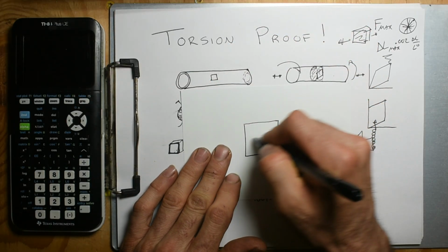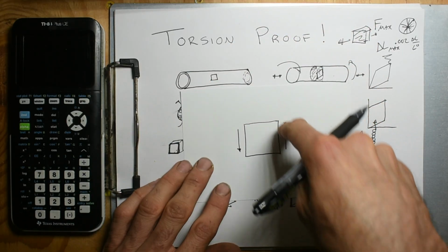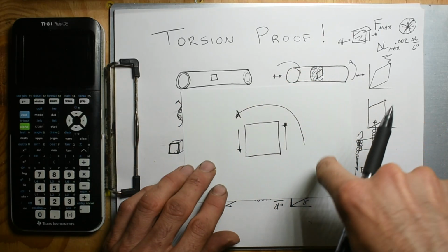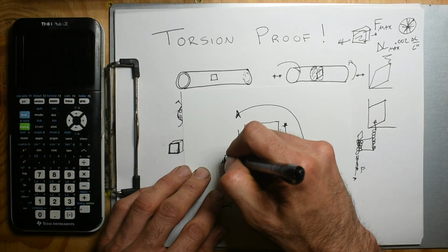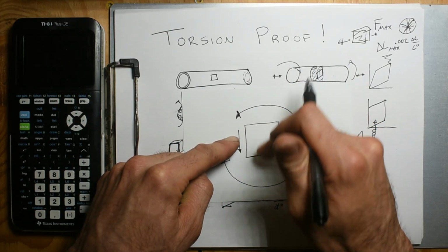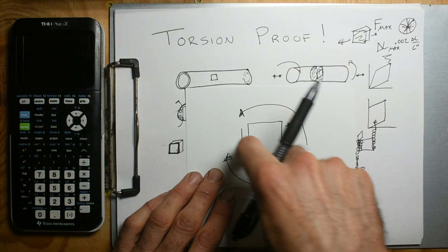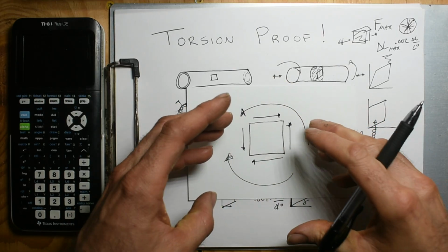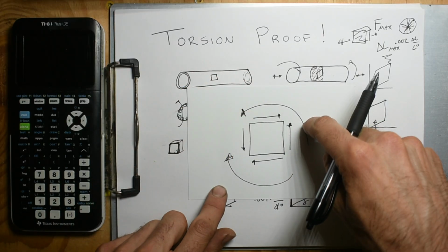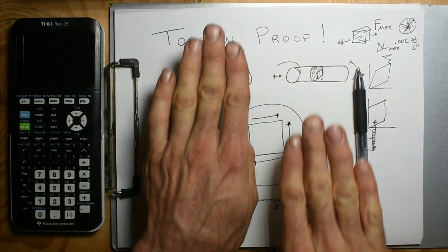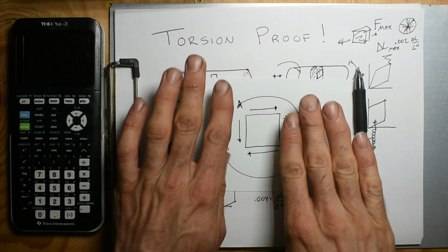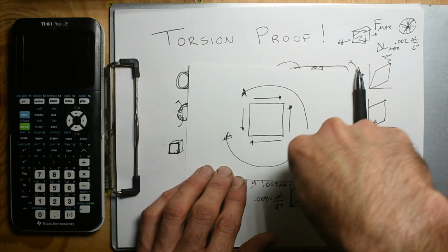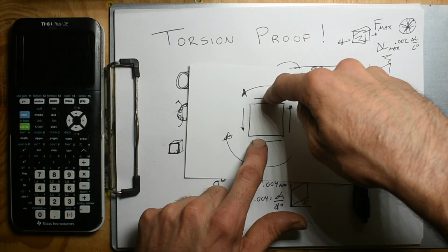So yes, I'm going to put an upward force, a downward force, and then this is causing a moment that way. See how this is causing a moment that way? I have to balance it with a moment the other way. And the only other two faces I can put stuff on is right there and there. And so I need to have a force that direction and a force that direction. I would memorize the direction of these forces from that. Pick two, the ones that are actually doing the visual thing that you're thinking it's doing, and then see what moment it generates, that arrow, and then make sure to balance it, and put the arrows on the opposite face.